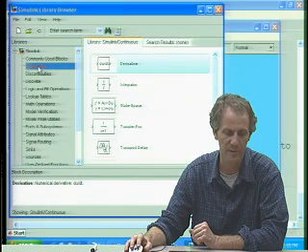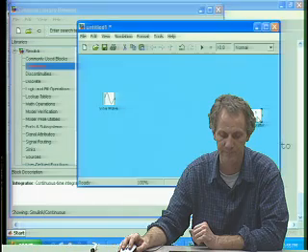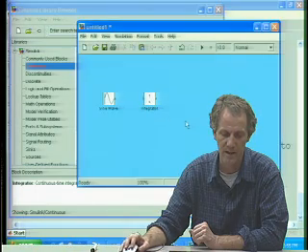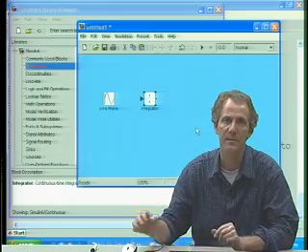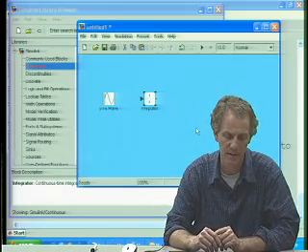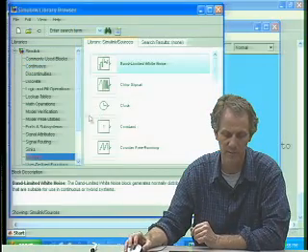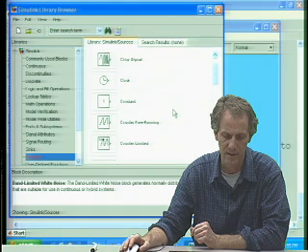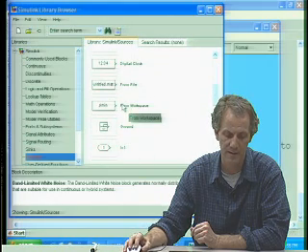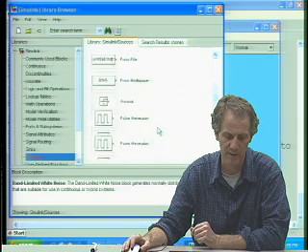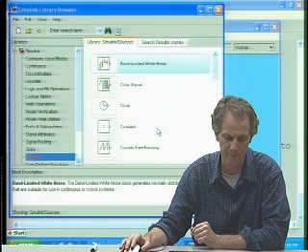All right, so there's my sine wave, and I'm going to integrate that using another math. Actually, it's in the continuous library. In the continuous library is the integrator, 1 over s. And it won't do to send this to the same sink that we had. It needs to go to some other kind of output. And I have a couple choices that would be good. I could send it to the workspace, and I'll do that in a second. Before I do that, I'm going to send it to the graphing tool.